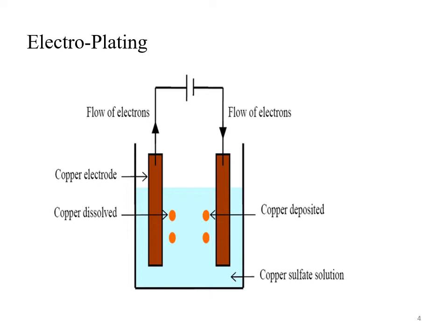That's why, for a very high strength material, for example, ultrasonic machining or abrasive jet machining are specifically suited for brittle materials, whereas water jet machining is basically suited for ductile materials. So material characteristics play a very vital role. The mechanical properties of the workpiece material play a very important role during the selection of the process.